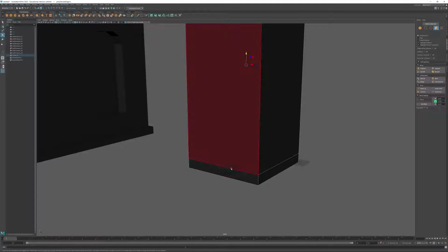We will grab the 2 faces and we will extrude them. We will go to Offset and we will, thickness rather. And we will move them out a total of 12. So that it matches.